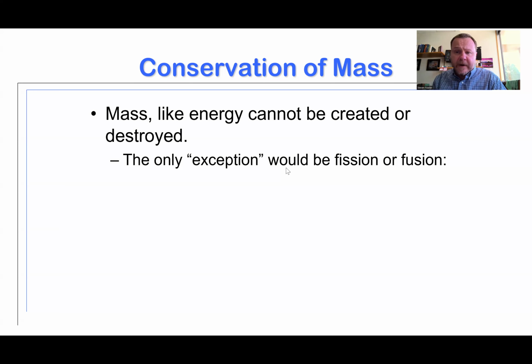If we start chapter 5 at this point, what is chapter 5? If chapter 4 is first law for closed systems, then chapter 5 is first law for control volumes. And again, control volumes are systems for our purposes. Control volumes are systems where mass can cross the boundary. Mass can come into and/or out of the system.